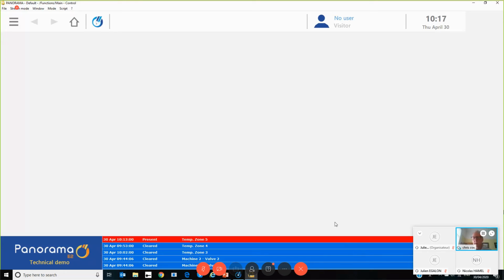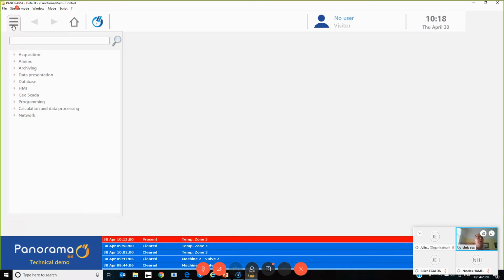It's just a little tick box that you put in the configuration to turn it on, and away it goes. So that's the only thing that we've done in the modification for here. So that's what your alarm windows would look like when you transfer them from a previous application. For navigation around here, I'm going to use the standard Panorama menu item. I don't know whether you're all familiar with this, but it allows you to explore around your graphic views that you've got within your system. I'm just going to look for the alarm pages. If I can spell alarm, A-L-A-R-M, there we go.